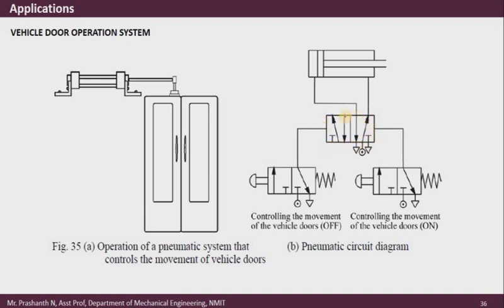The reason it is called pilot operated is that I am not directly actuating this valve. The input is given with the help of another valve, a push button valve.